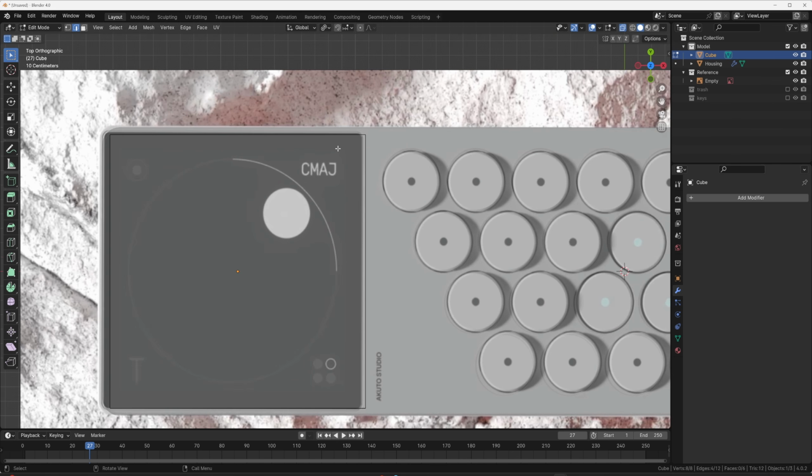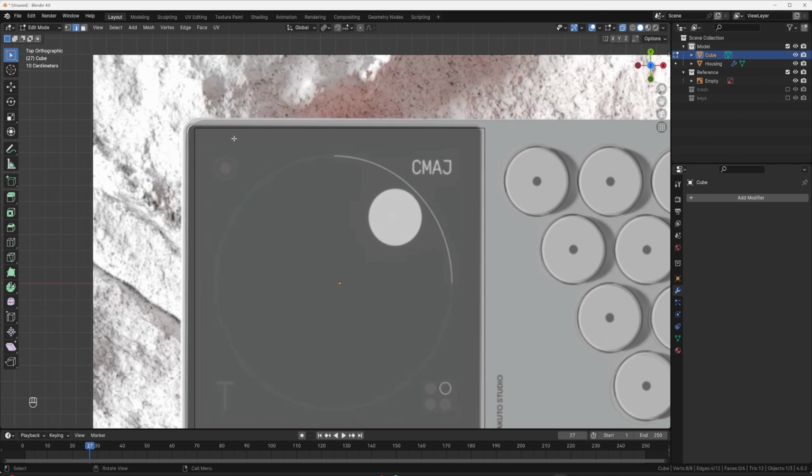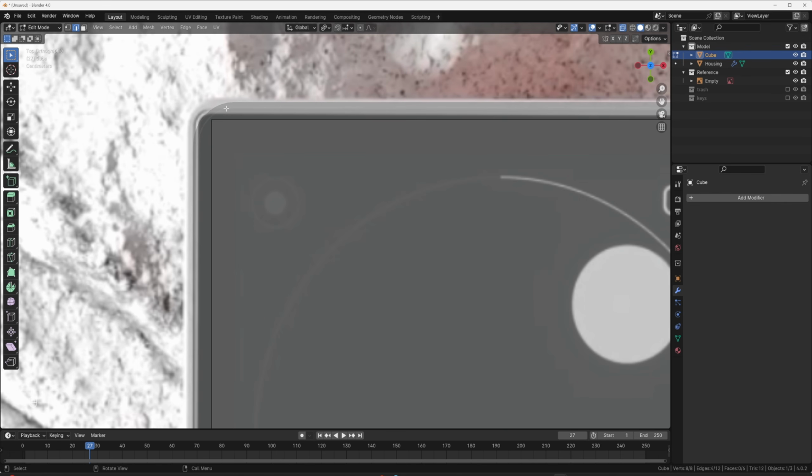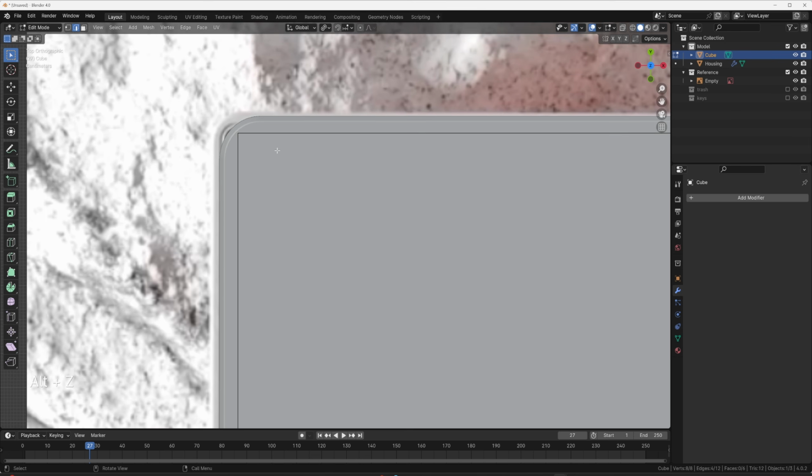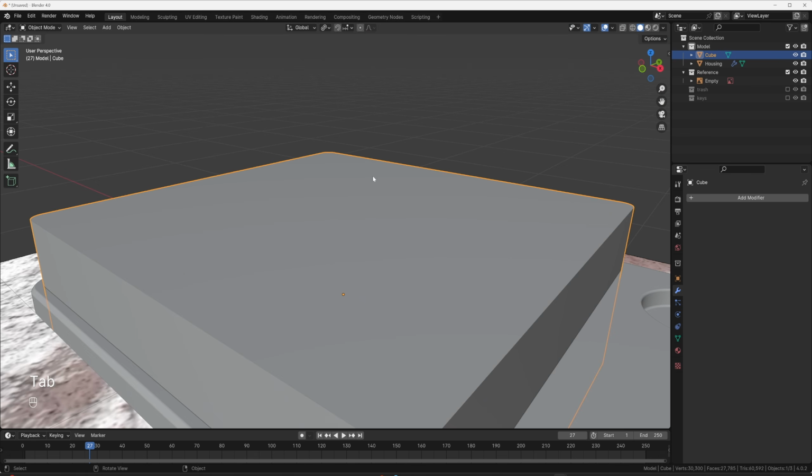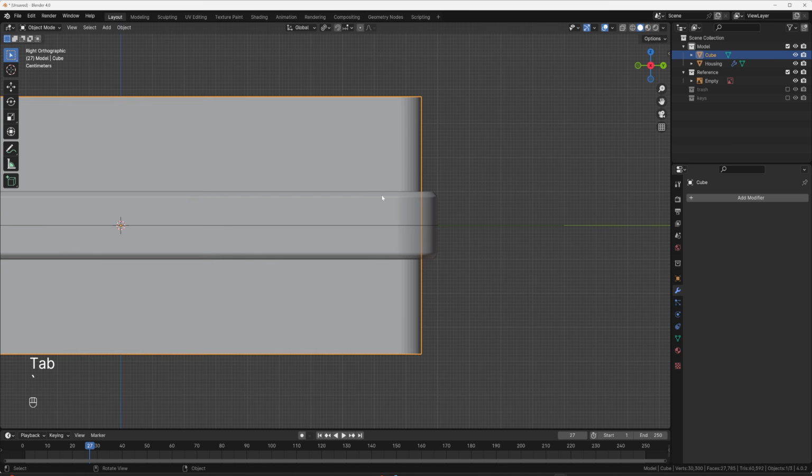So while I've got this done, I want to match kind of this bevel right here. So actually I'm going to go out of Alt Z and then just Control B bevel and just get something that looks good with that. I think right about there looks good for me. And then I'm going to scale it up to 10 segments on the bevel using the middle mouse wheel. Just hit select. And then all I want to do with this is just barely cut out from the top.